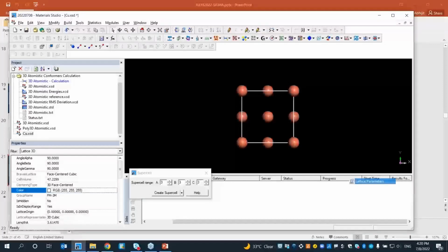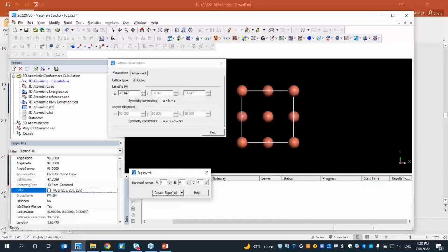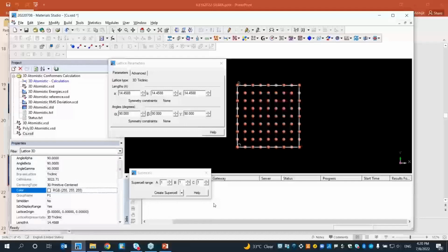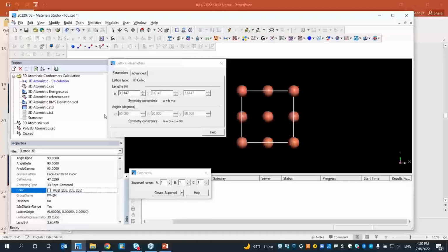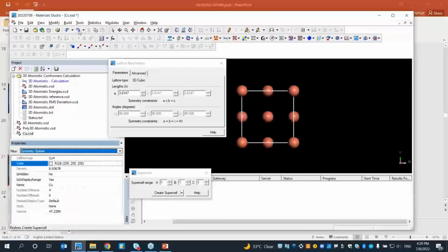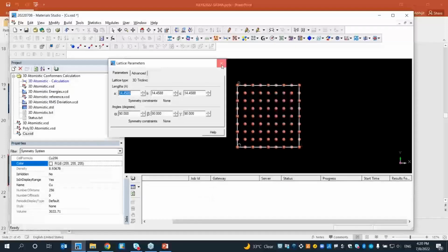And if you go back, your number of atoms inside this lattice was 4. So you are now putting it 4 times 4 times 4. Then you know the number of atoms is 256. So you have a 256 atom structure, and you want to make a surface of it because you want to see an adsorption. So basically you have to cleave a surface. All of this Material Studio's visualizer or modeler can do.